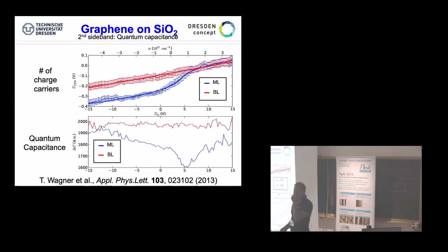Well, we measure the capacitance of each of these layers. What is that? The quantum capacitance that we measure here. For this, we have mounted the sample, as you can see, also in a field effect transistor device. That means simply we have a gate electrode applying exactly the DC voltage, cranking up the voltage from minus 15 to plus 15. So imagine there's a field on your sample that comes up, and what does it do? It does produce charges, exactly the same way as we had before in the contact experiment with the oxides.